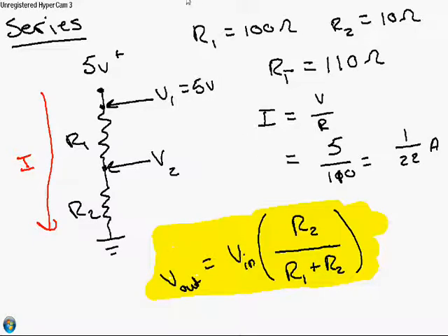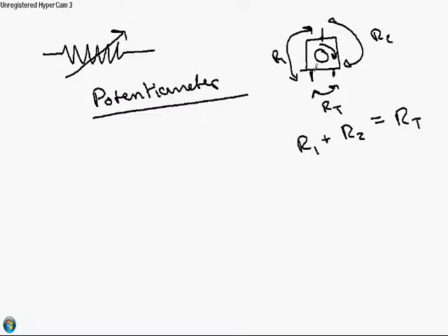Yes, it is a series resistor, which means this thing can effectively act as a voltage divider. So if I take this, let's label the parts. This thing right here, this arrow, is the wiper. So I'll make a note in a different color so you don't get confused. This is called the wiper. It's the thing that slides across. Oftentimes it's a carbon track to change the voltage across, or to change the resistance across the device.